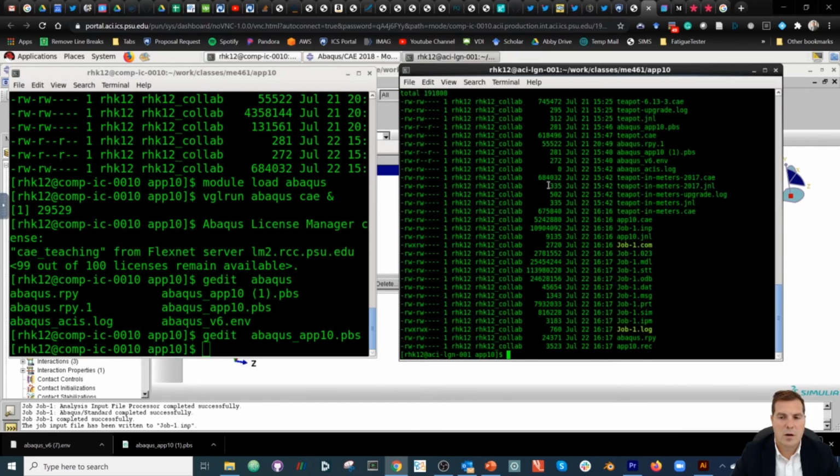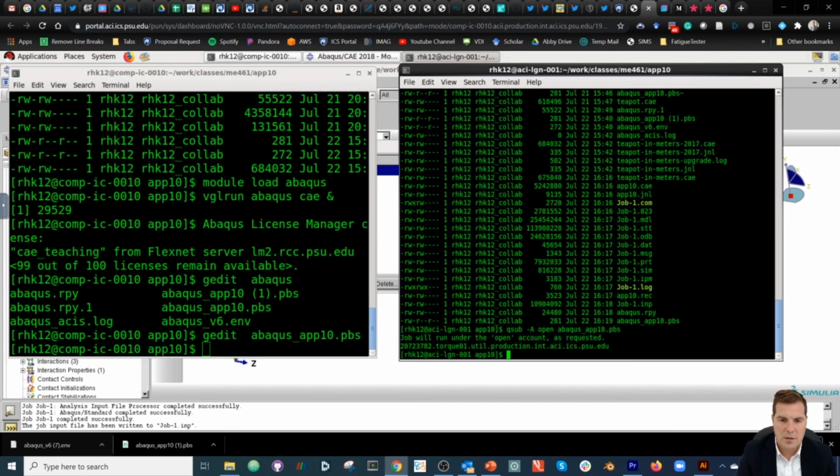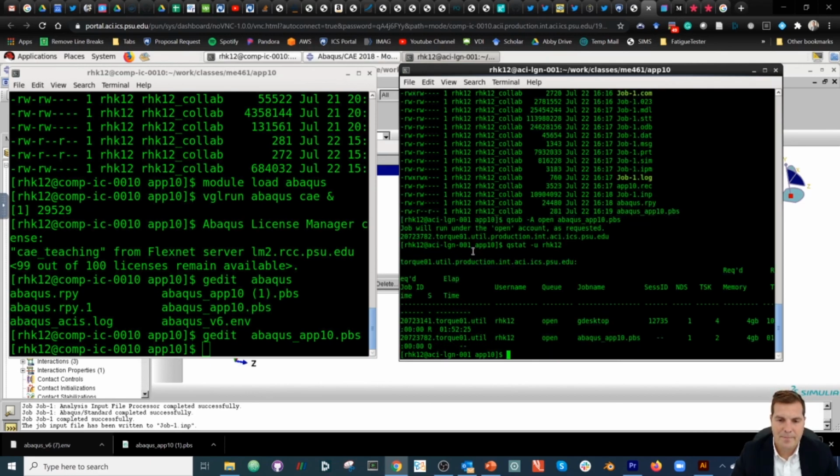Go back to our ACI-B window, and we can do qsub -A, we're going to use the open queue, abaqus_app10.pbs, and enter. So we get our job number or ID. We can do qstat -u, your username, and that tells you that it was submitted and it's in the queue. Okay, so I'll let that run, and in the next video we'll come back and post-process.